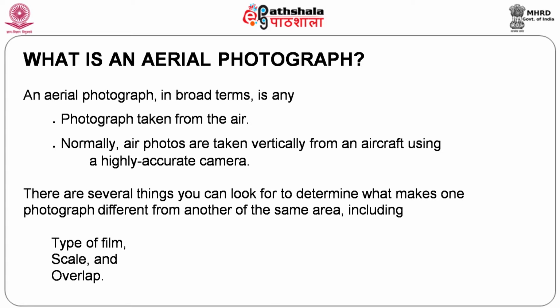Now, we have different types of photographs, but before that let me tell you what the importance is. Previously, for a long time, photographs were taken using normal films, of course exclusive films meant for that, so they are film based. The most important concept in aerial photography is the scale of the photograph and the overlap of the photographs. When I am taking a satellite image I do not bother with the scale, but when I am photographing the surface from air, I have an issue, namely the scale factor. We will see the detail later.